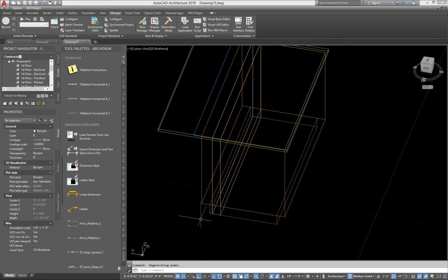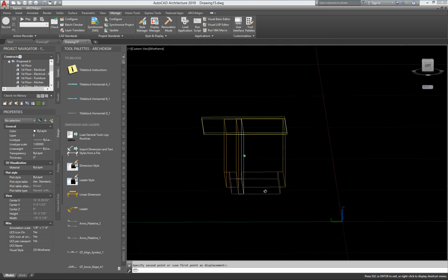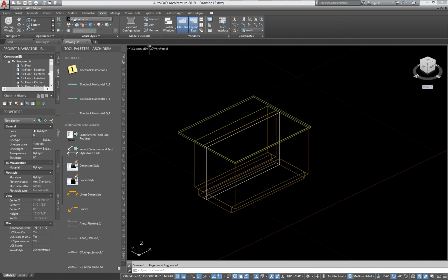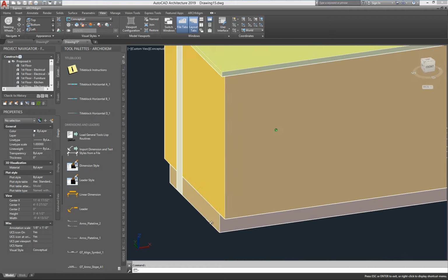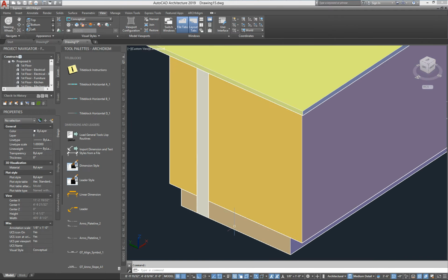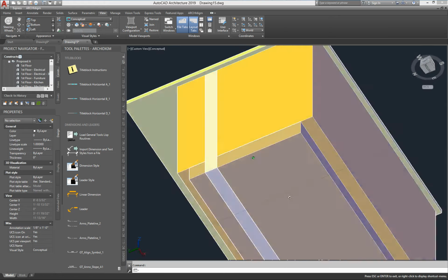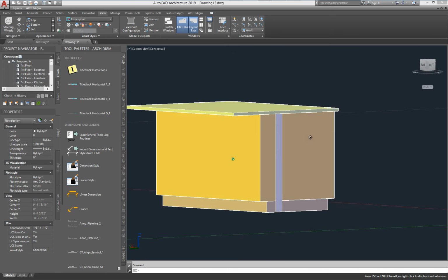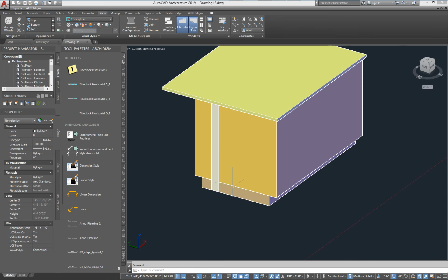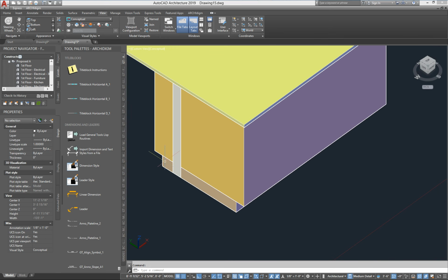All right, so let me move that back out. Now I might want to move that back in. We'll take a look at that in a minute here, but I'll move that back out. So what I've got here is now a good island. If we go to conceptual, so we've got this. Now I'm not keen on seeing that wall sticking through like that, so I'll pull that back in and make some adjustments. But everything else is looking good. If we look underneath, you can see this probably will work. This overhang will probably need some structural support, unless you thicken it all up with plywood, but that's up to you. Okay, so what we need to do is add some kicks to the ends here.